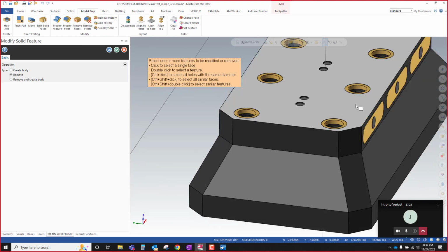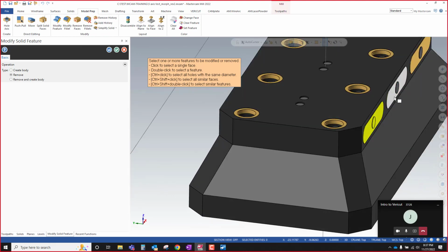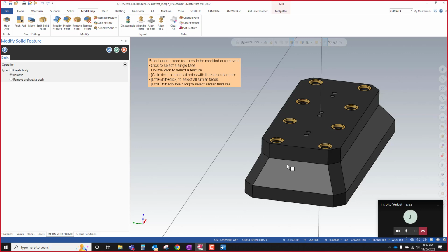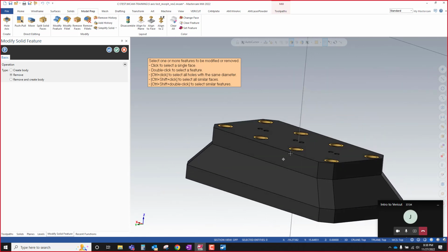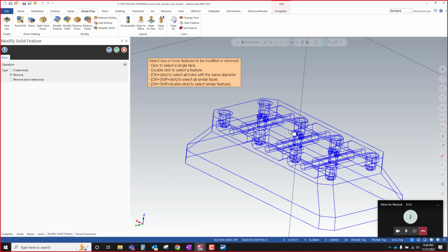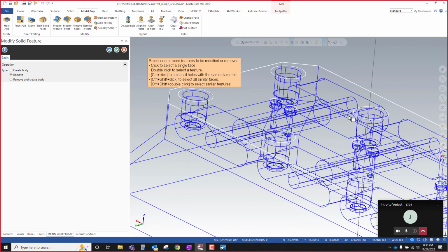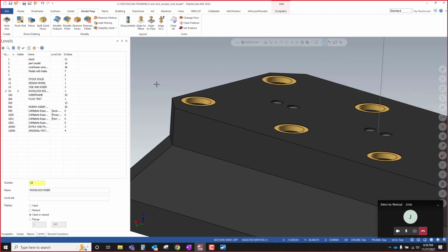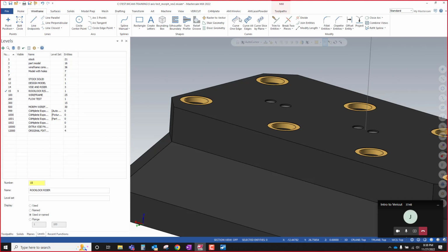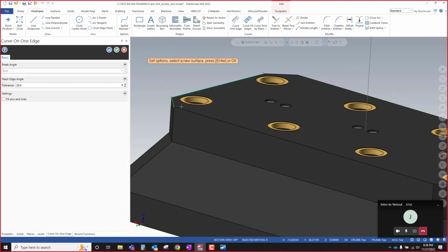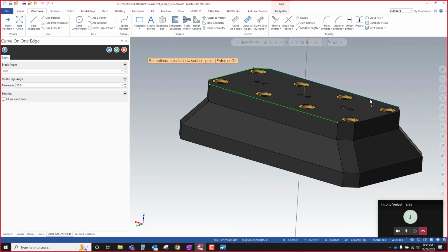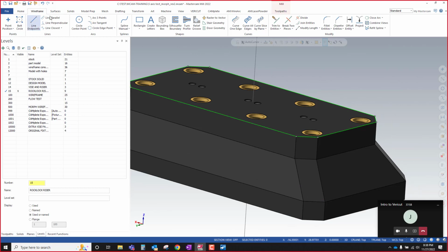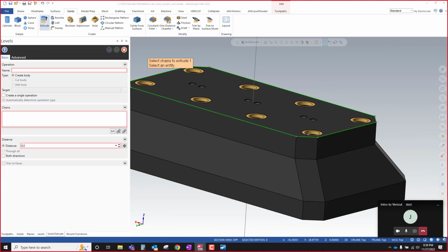And then I'm going to take this top contour, the top line, extrude it, and then Boolean add it to get rid of that stuff. So I cleared that out. I could do the same thing with all these internal features, but eventually I'm going to run into features I just can't get rid of. So instead, I'm going to go to wireframe, just curve one edge. There are only a few lines here, 8 lines, so I connect these edges, and I'll do a solid extrude.